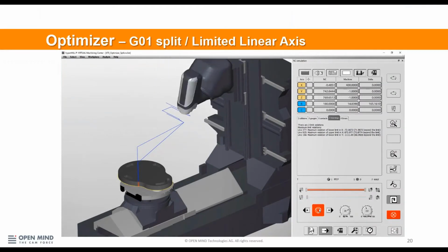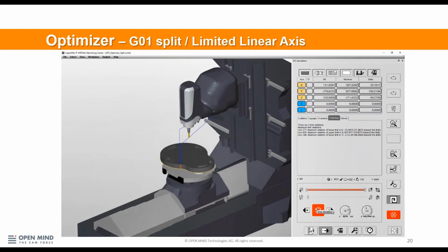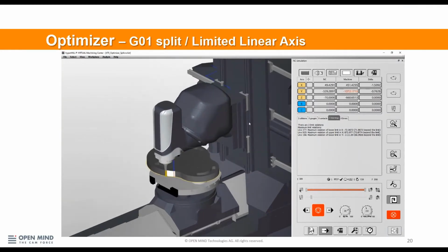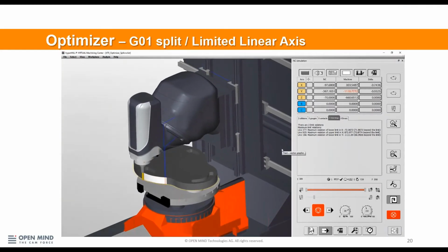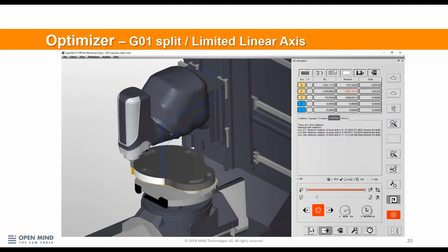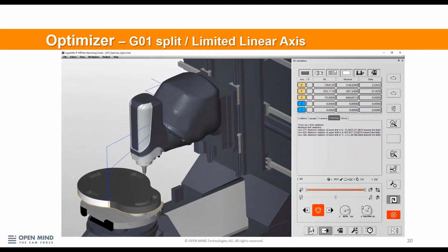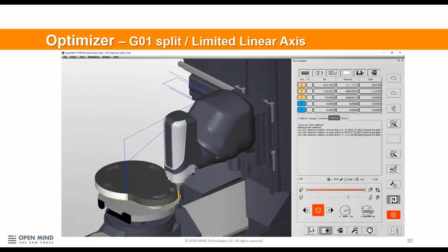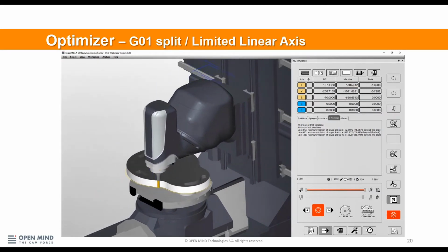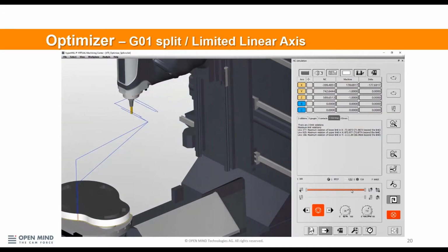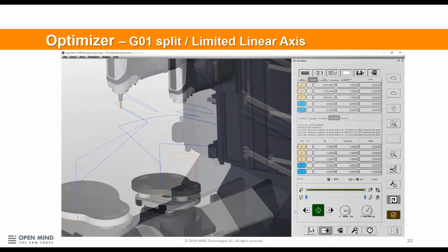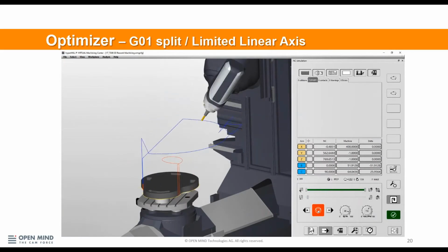So now in this example, our first simulation shows us a warning that our machine violates the axis limits of this machine. I'll use the feed rate knob to increase the speed of our simulation. Now, the part can theoretically fit into the machine work envelope, but the programmer's tasked with trying to solve this issue. Does he need to make unique work holding? Our next simulation shows the result with the NC optimizer.